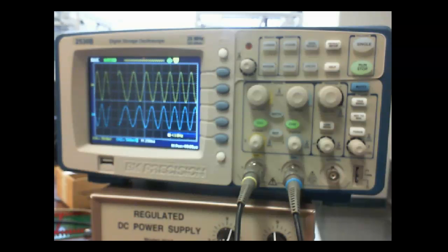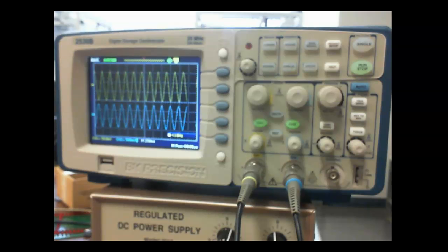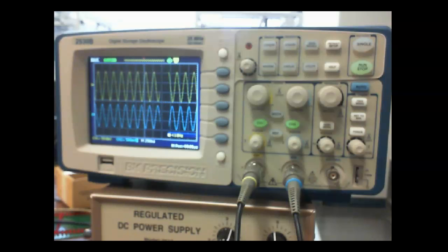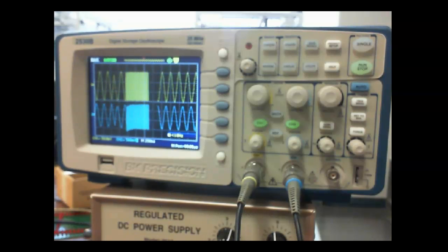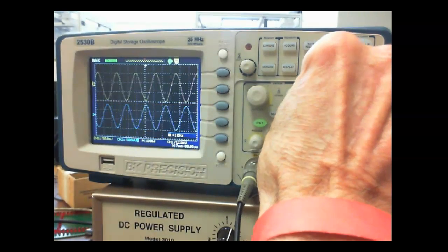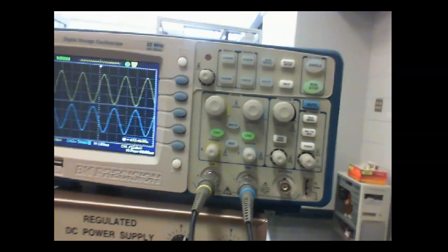Our problem is designing these things. There's a lot to design, especially when it comes to impedance matching. Impedance matching is really rough on these things. So that's one advantage that a FET has over a bipolar transistor: you can match impedance really well. These things are not easy to design, but once they're designed, they're fairly easy to calculate to see what they're supposed to do. So that was really neat.